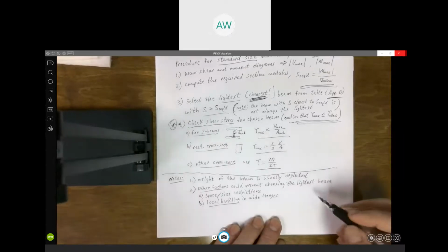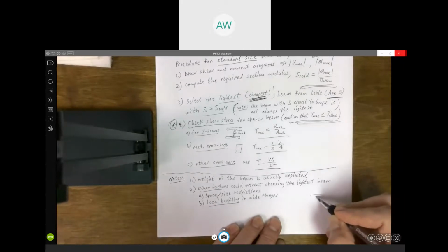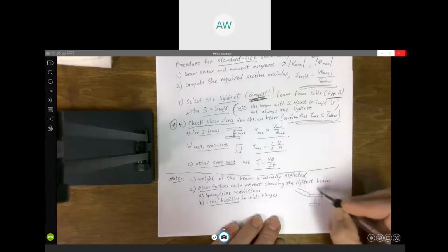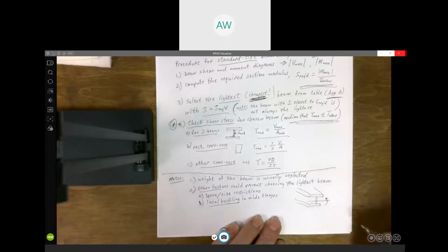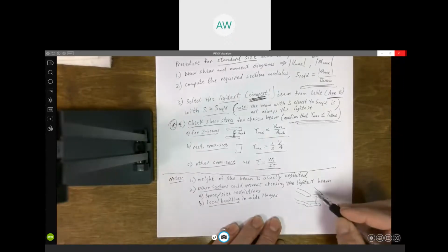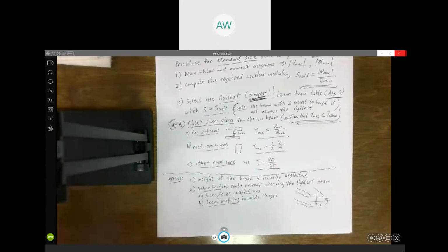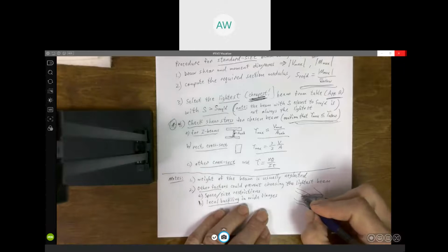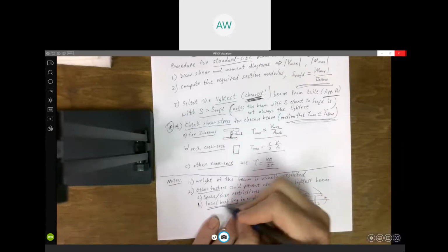Say we've got this I-beam with really wide flanges on it. If we bend this thing this way, this top is going to be in compression. And what you could see is this really wide, thin flange could, I don't know, ripple, look like a wave. That's what we call local buckling.